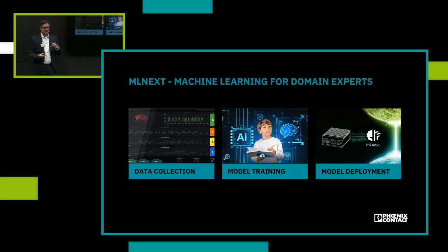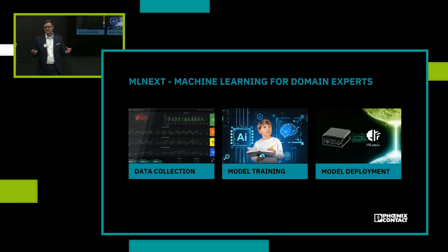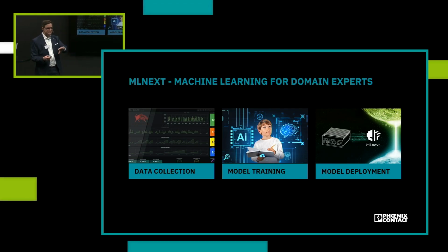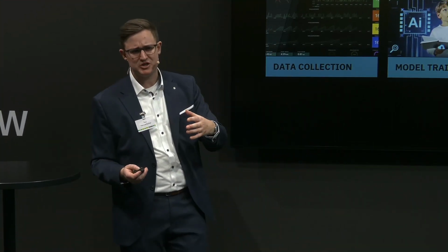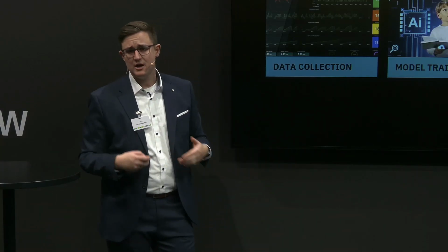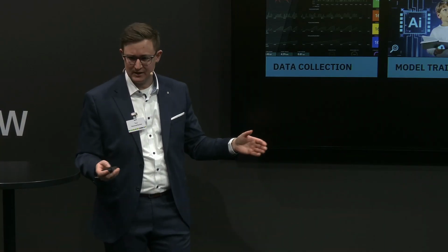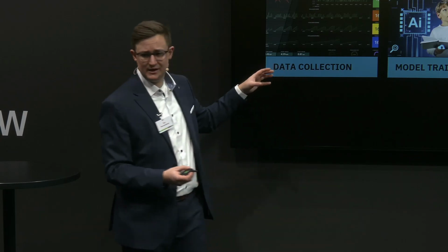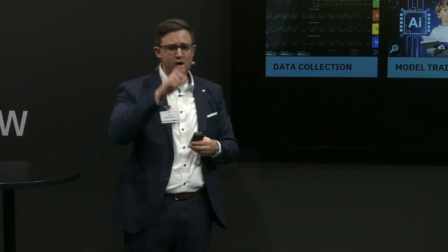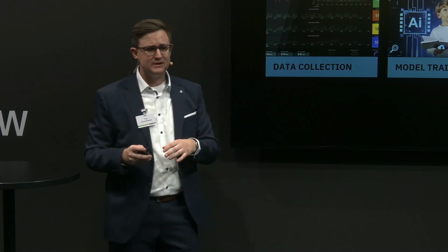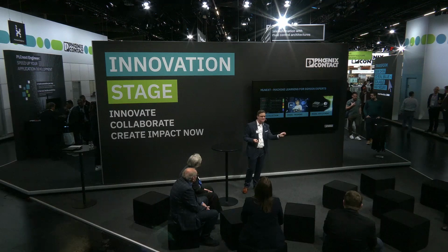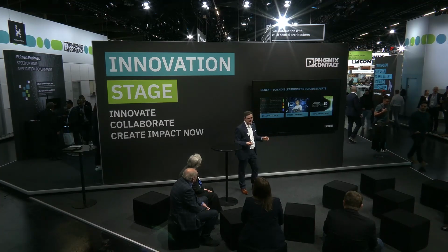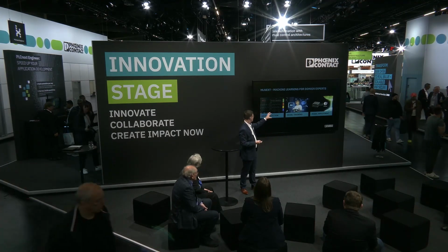We want to have the AI as an experienced maintenance guy that comes into the offices, that comes into the production lines and says, something is unusual. That's an unusual vibration. That's untypical. Or maybe I hear a noise, I hear something that is not quite typical for the normal behavior of the machine. And this information is already encoded in the data. So small peaks in the vibration or a little bit unusually high energy consumption because the friction of my drive shaft is a little bit tougher than usual. And those are exactly the first signs that we want to analyze with our AI.